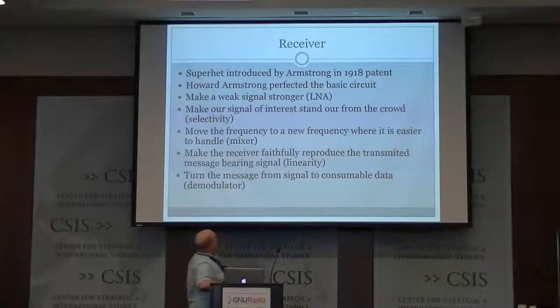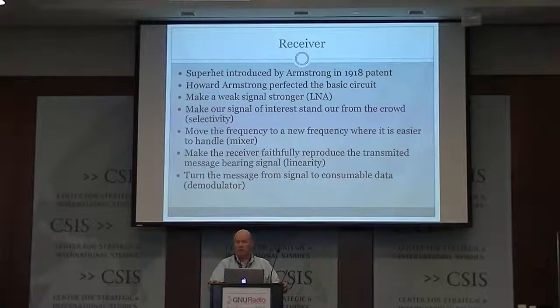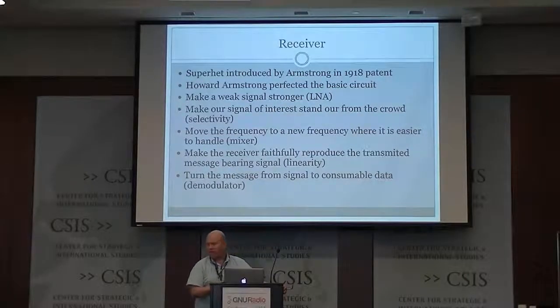Okay. All right. And furthermore, I have to know something about where you're transmitting, or what frequency you're transmitting on, because do you think I want FM radio and every television station and every police and fire truck, etc., coming in my receiver along with your message? No. So the filtering out of all those other signals is the selectivity that is provided in a receiver.